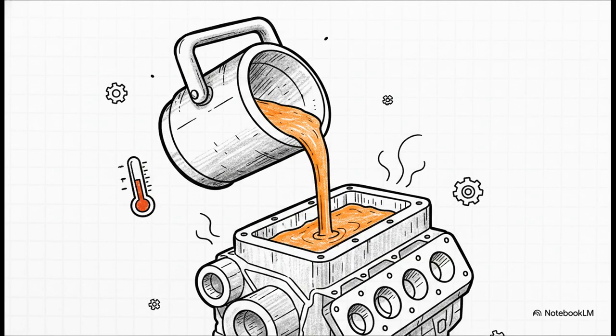Well, the secret is fluidity. That extra carbon dramatically lowers the melting temperature of the alloy, down to somewhere between 1150 and 1300 degrees Celsius, which is actually considerably lower than steel. This creates a highly fluid liquid metal that is just incredibly easy to melt and pour. Because it's so fluid and because it shrinks very little when it finally cools, cast iron is absolutely perfect for pouring into complex, highly intricate molds. It allows us to create heavy equipment bases or complicated engine blocks that would be nearly impossible or prohibitively expensive to forge or machine out of a solid block of steel.